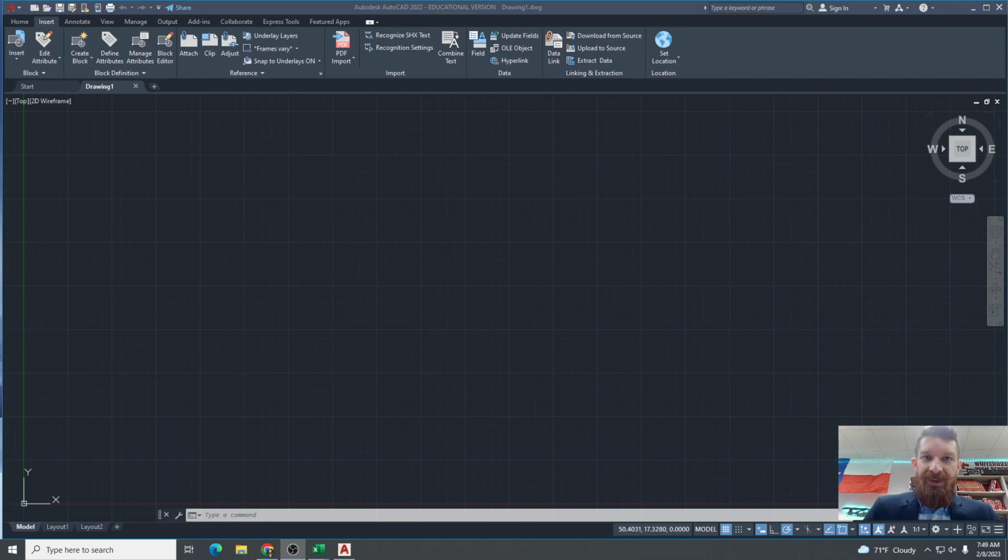So if you think back to early in this class when you were still sketching by hand, we started doing multi-view drawings, and that shows three views of an object. It shows the front view, the top view, and the right-hand view, as well as an isometric up in the corner, so that you can see all three faces of the object on a 2D sheet of paper, but they represent all three dimensions of the part. So if you want to grab your old engineering notebook and look back at when we were doing multi-view drawings by hand, it'll probably come in handy for this unit.